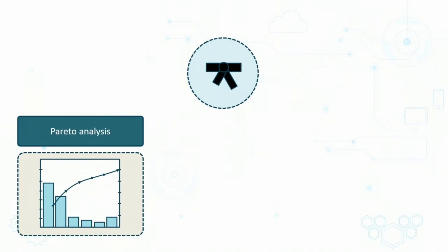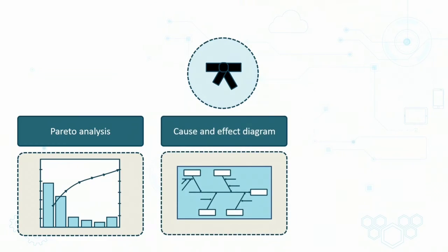The return bend is a U-shaped piece of tubing that is connected to the straight tubing by brazing, a procedure that is similar to soldering. The team decided to focus on the brazing process. The team also performed a root cause analysis with a cause and effect or fishbone diagram. Team members listed the materials, methods, machinery, measurement, manpower, and environmental influences on each step in the brazing process.